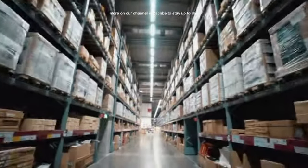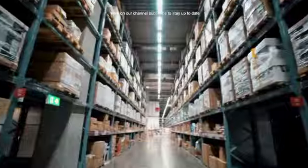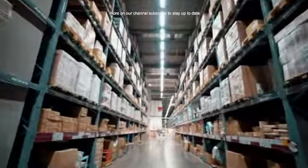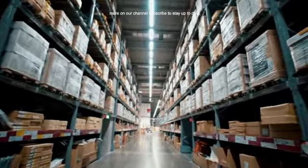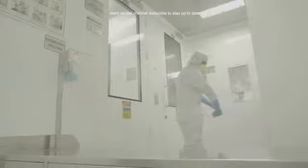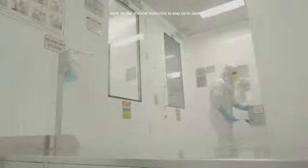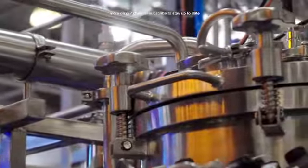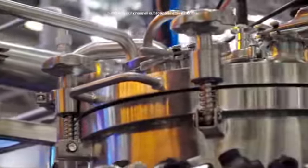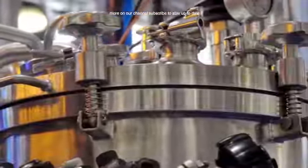Think about dedicated areas for receiving raw materials, manufacturing, packaging, quality control, and storage. These areas should be appropriately segregated, often with physical barriers, airlocks, and differential air pressures, especially when handling potent compounds or sterile products. Surfaces, walls, floors, ceilings must be smooth, impervious, and easy to clean and sanitize effectively.